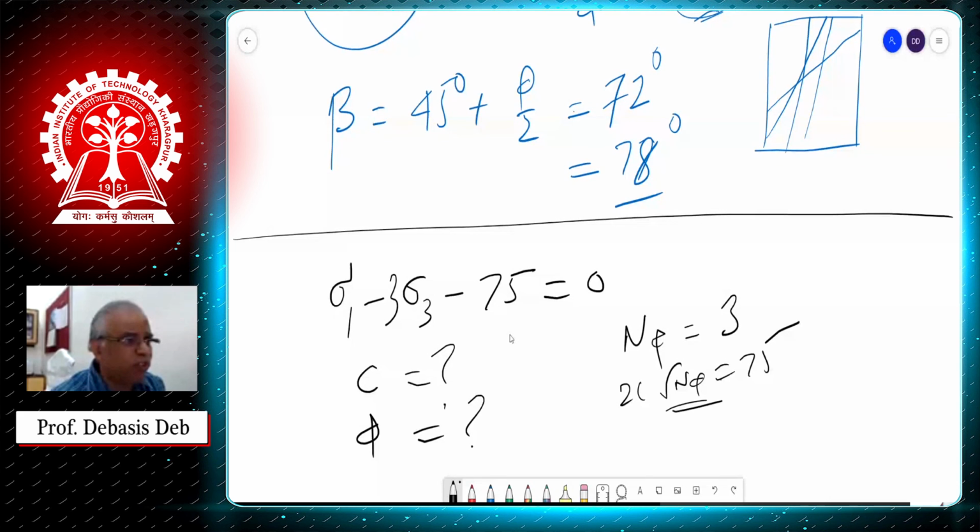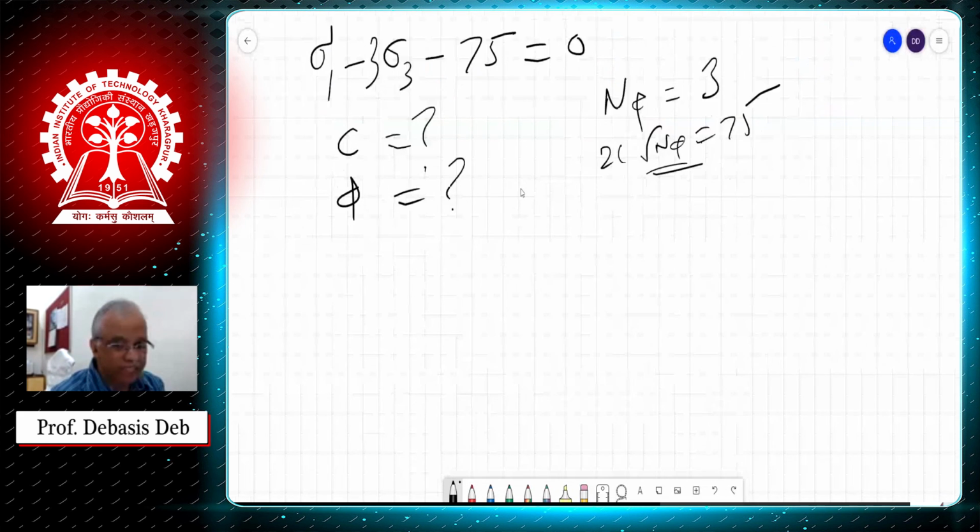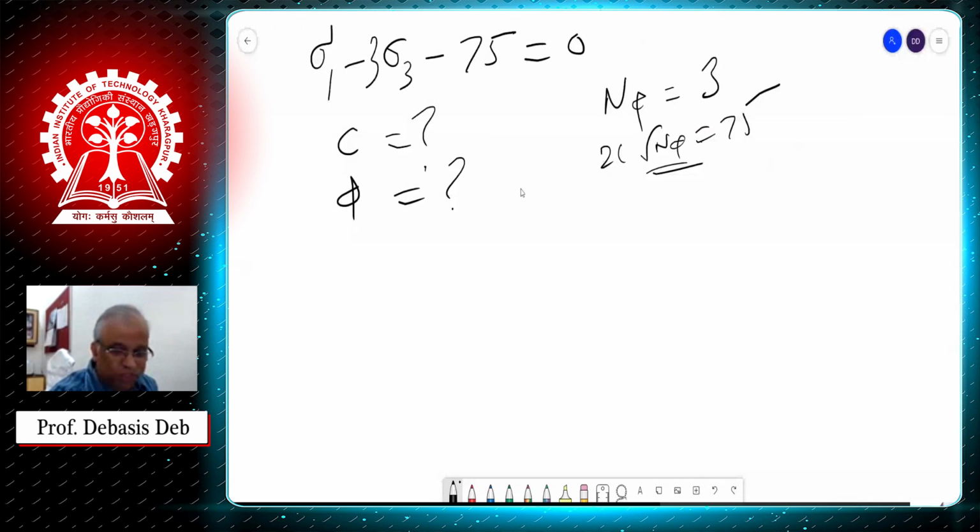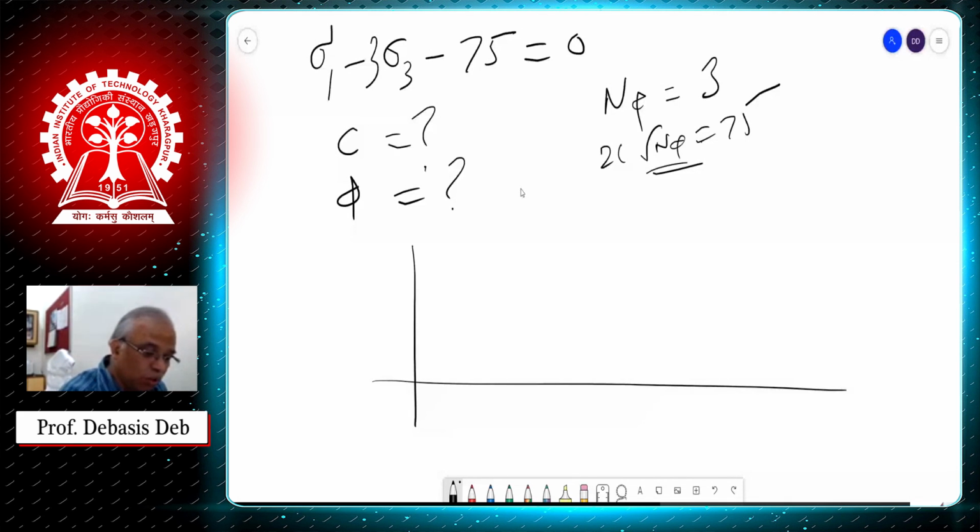Last thing before we go, since we are in this, I showed you here with one test only, but normally we do not do a single test. We do multiple tests because in a rock type material, you never believe results with a single test.